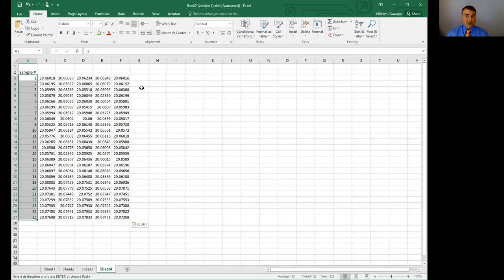And there are two different ways the process can be off. One is the mean can be shifted, so it's not what it's supposed to be. The other is that the variance could increase or decrease in a way that we're not expecting, indicating the process is out of control as well. So you make both an Xbar and an R chart.